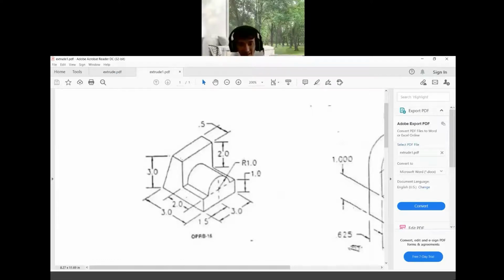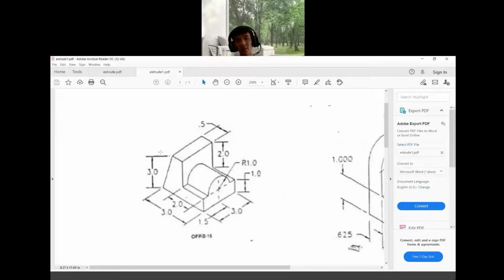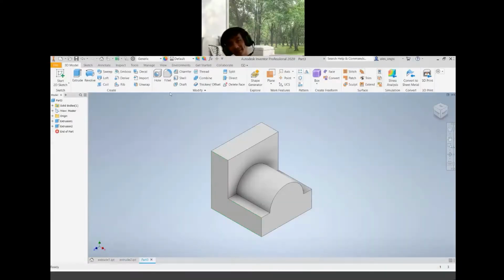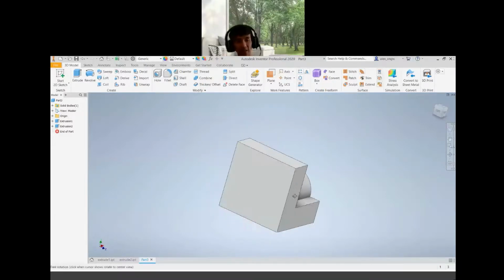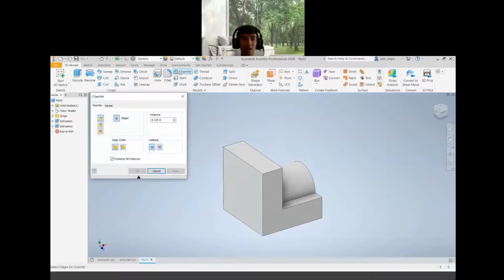One, you can select this surface. Another one will be this surface itself. So both are correct, no problems. So maybe I select from this surface. Okay, I select from this surface. Just click on the surface that you intend to turn into the work plane.